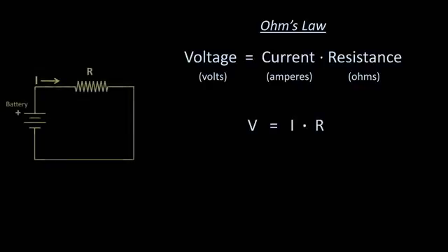Here is a simple circuit. The battery, represented by 4 lines of alternating length, provides the voltage. The resistor is represented by a zigzag, which interrupts the normal unimpeded current, represented by I, as it travels clockwise, starting and ending at the battery. An extremely simple Ohm's law problem might give us the voltage of the battery, suppose it's 12 volts, and the value of the resistor could be 4 ohms, which is frequently represented by the Greek letter omega, and we could be asked to solve for the amount of current traveling through the circuit.